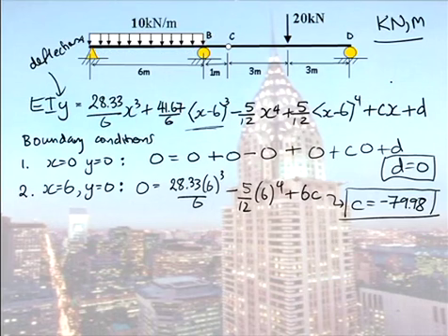If you come to this point here and go, oh, I've changed my mind, I want to work now in millimetres, this 6 here would become 6,000. So what you think is you can multiply everything by 1,000, but you can't, because some of these numbers here are already a moment, for instance. They may be a moment term, so then you would have to multiply it by 10 to the 6. So don't halfway through decide you want to change units. At the very beginning, decide what you're going to do.